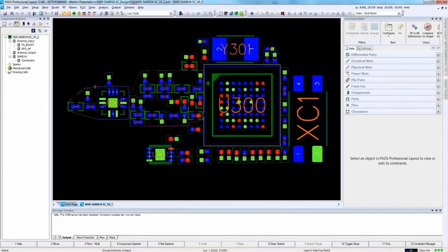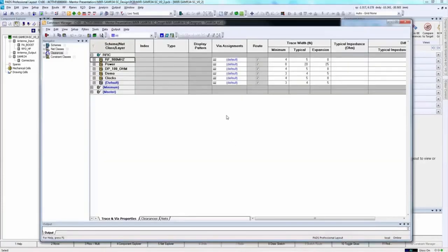And this is a way to group, and something that I love about PADS Professional. It really has been a great tool in grouping similar nets that have certain parameters that are similar, speeds, time of flight. We have a constraint option in PADS Professional here.